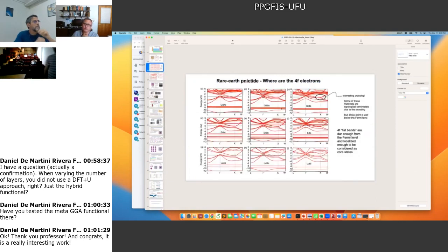Well, it has to do also with the position of the d bands and the p bands. Bismuth gives you a p band that is higher in energy, that will be closer to the d band. But then the lattice parameter also increases, right? When the lattice parameter increases, you see the dispersion of the d band also decreases. If you go from erbium arsenide, you see a dispersion here of the electron pocket. If you go to antimonide, the dispersion decreases.